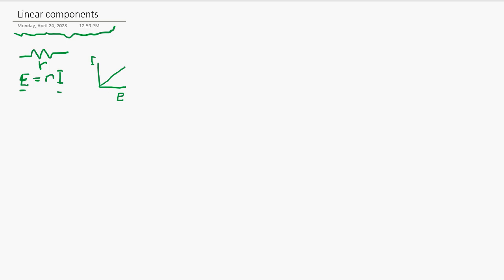For example, in order to sense the current, we use a very small resistor like 0.01 ohm. Making such a small resistance is very difficult, because if you have a 10% variance in the resistor value, the measurement changes by 10%.